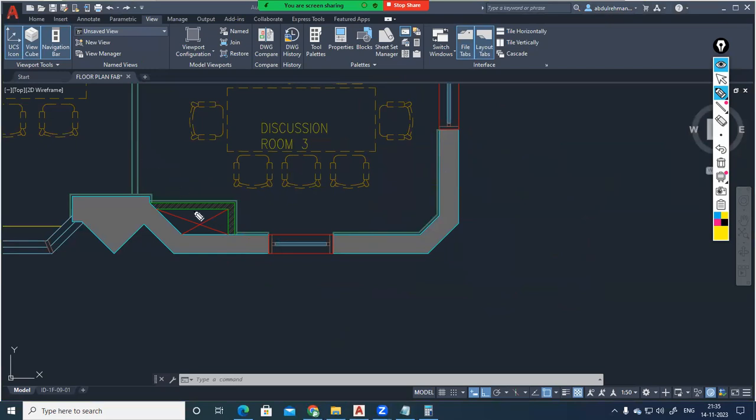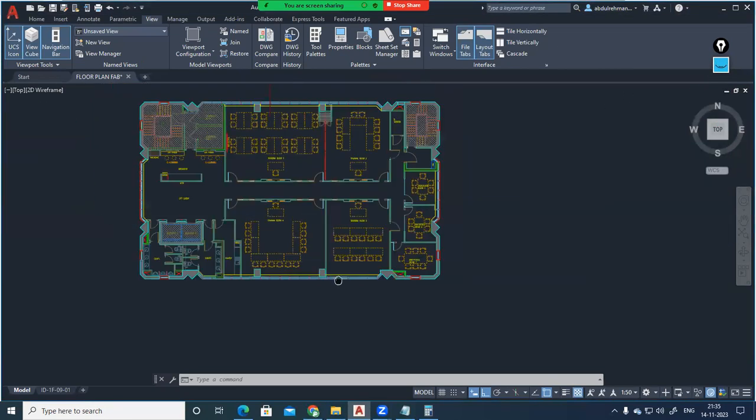Why is it important? Because if we are not providing air conditioning inside the shaft, the partition heat transfer will enter into the rooms. So we should consider that. And as per the location of the shaft, we route the services. So shaft location is mandatory, and that is our building shaft.